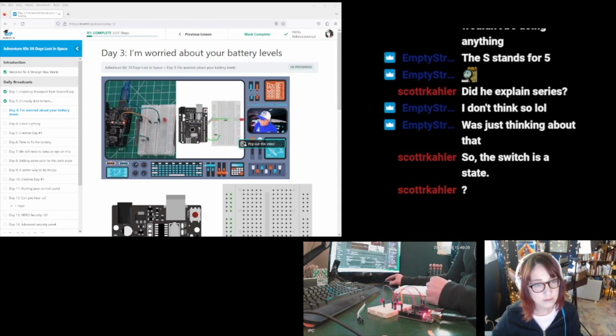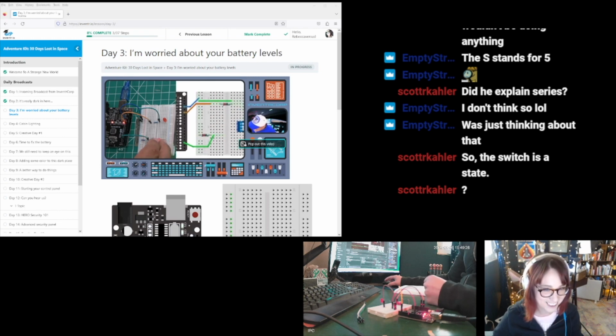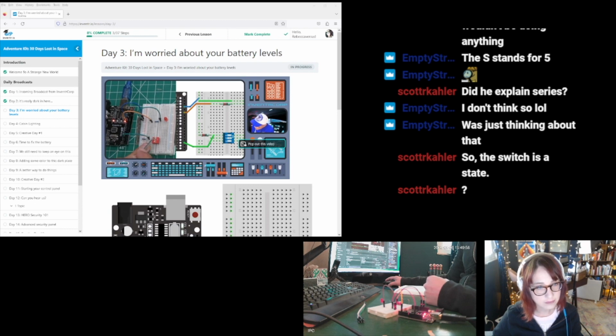So, what we're going to do, returning over here to the breadboard, is take our dip switch, so that the first of the 3 switches, switch 1, is spanning across the gap here in the breadboard, so that when the switch is in the off position, these rows on the left are not connected with these rows on the right. But for example, if I take the switch and I flip it to on, like so, let's put that switch on.